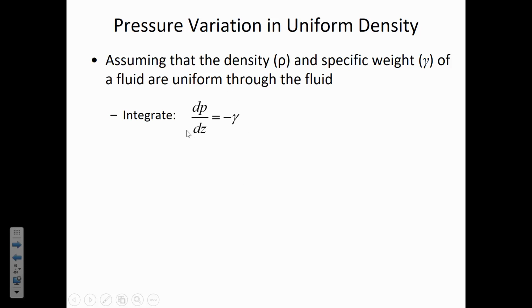Now, this hydrostatic equation, if we integrate it, there is a relationship that we call piezometric pressure. The piezometric pressure has two terms: the pressure term and then this elevation head term. What it says is that in a tank of water, if you go from place to place in a tank, there won't be a change in the piezometric pressure if this water isn't moving.